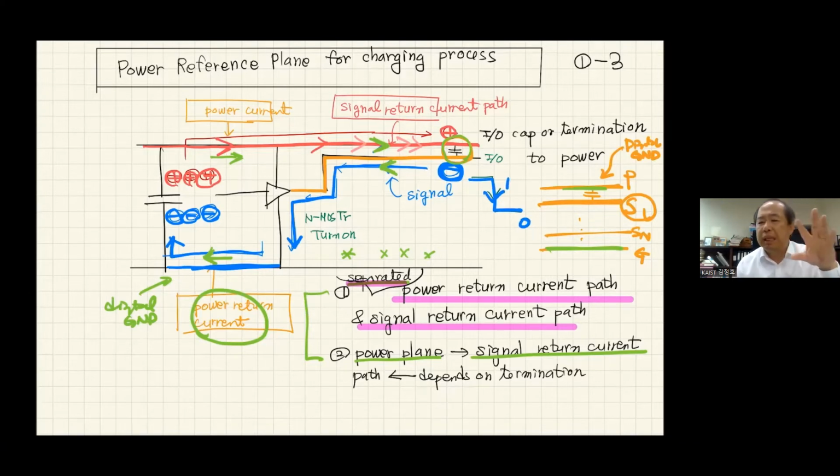When you are designing your circuit, in the circuit diagram, we never consider the return current path. We assume that return current will come back anyway through the minimal impedance path. But that's not true. It can go through any metal line, because of resonance and parasitics. So it is a very difficult part. I think 99% of signal integrity and power integrity problems may be connected to the understanding of the return current path and how you design it.